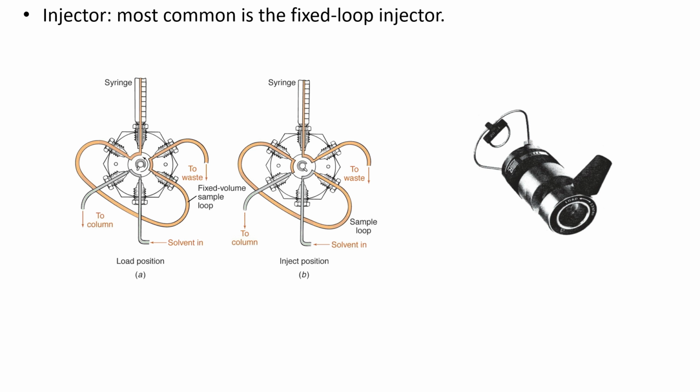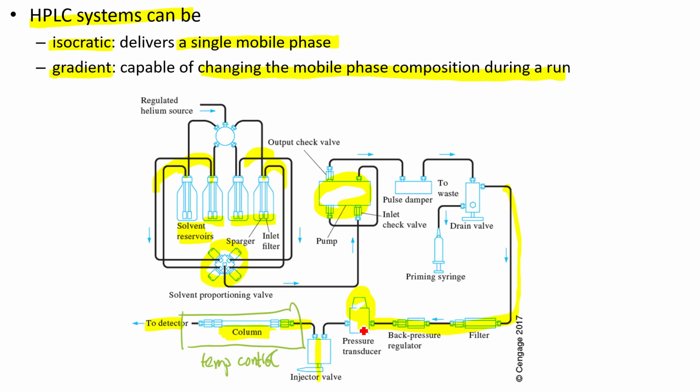Okay, then we go to the injector. We've got to create the pressure or introduce the sample into this pressurized loop. So I'm going to go back. So running up to here, we typically have anywhere from, just stick with traditional chromatography, from 2,000 to 3,000 PSI of flow. So whatever our flow rate is, maybe a typical flow rate is 1 mil per minute of the solvent. That's coming in and going into the injector.